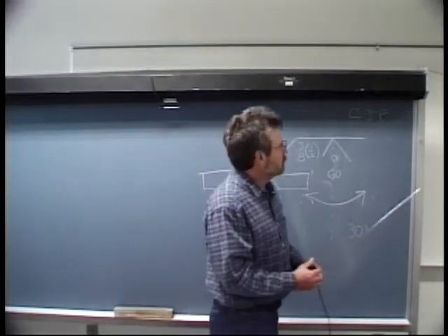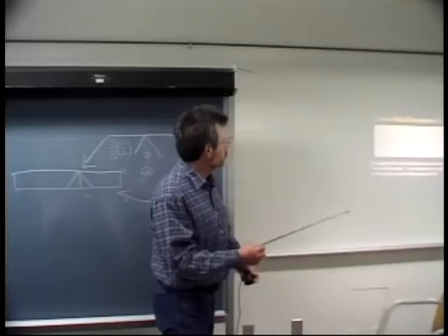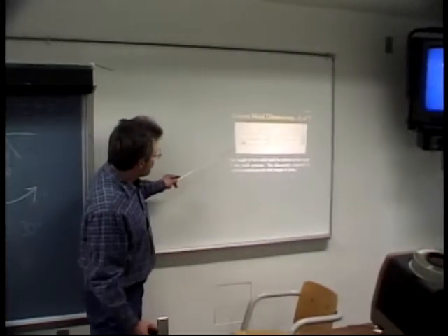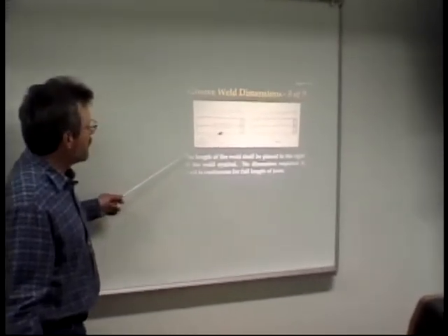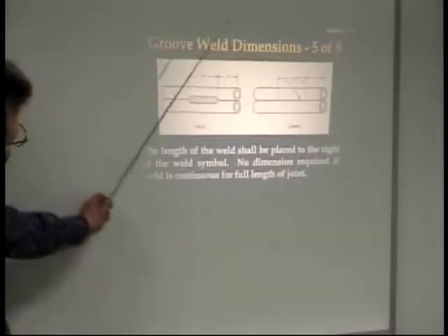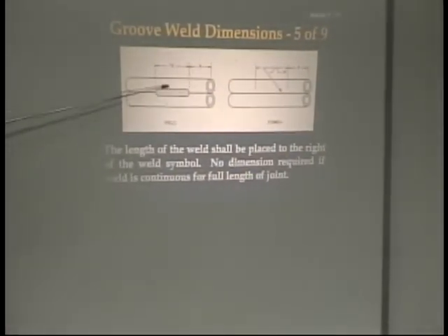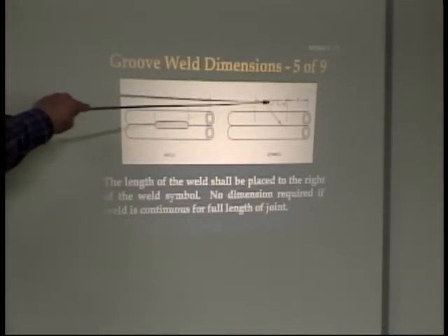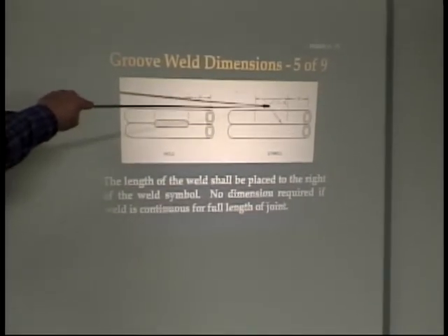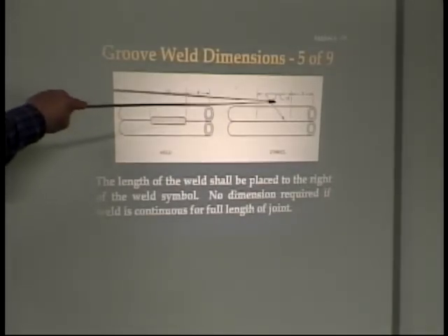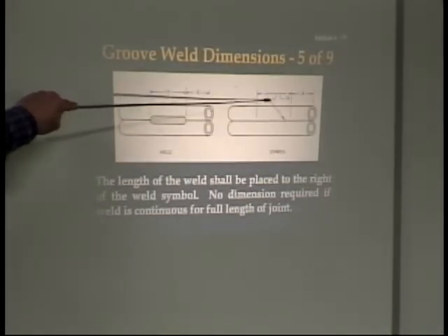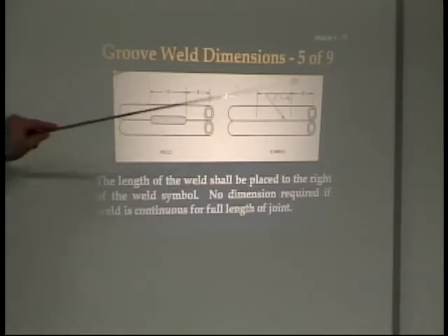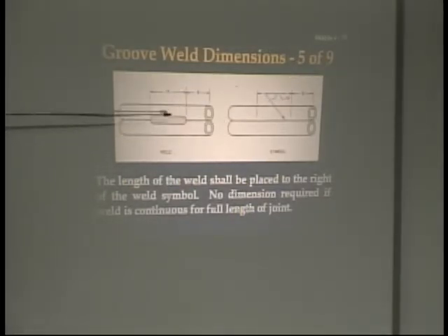And this is what my slide here on the board shows you. Here we've got two pieces of pipe, and I've actually run into this. I've had to do inspection. Imagine these standing vertically up. These are called stitch welds. Here's this welding symbol for a flare bevel groove, because both of these pipes are rounded, and that's what the rounding of the weld symbol shows. And so they have to have a weld 16 inches long, 8 inches from the end.